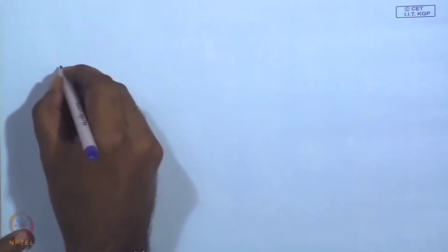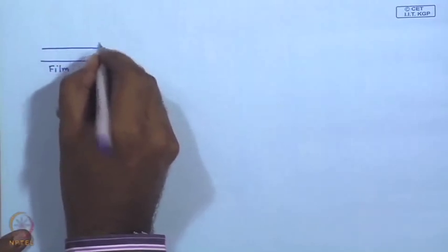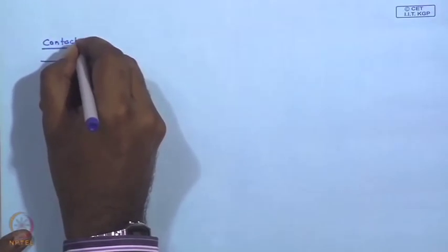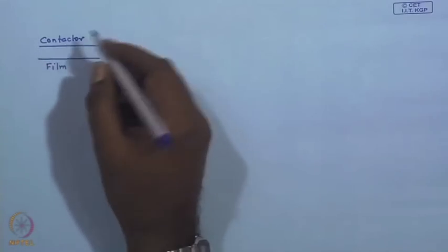Okay. So, what was considered was that if this elastic contact instability has to be used as a viable patterning technique, the structures arising out of elastic contact instability have to be aligned. And the simplest approach that was taken was, so this is the regular setting. You have an elastic film, which I am writing now as a film, you understand it is an elastic film. This is a contactor. So, the attraction between the contactor and the film, the adhesive or the attractive interaction which is responsible for the manifestation of the whole instability, is uniform between these two now in a regular case.